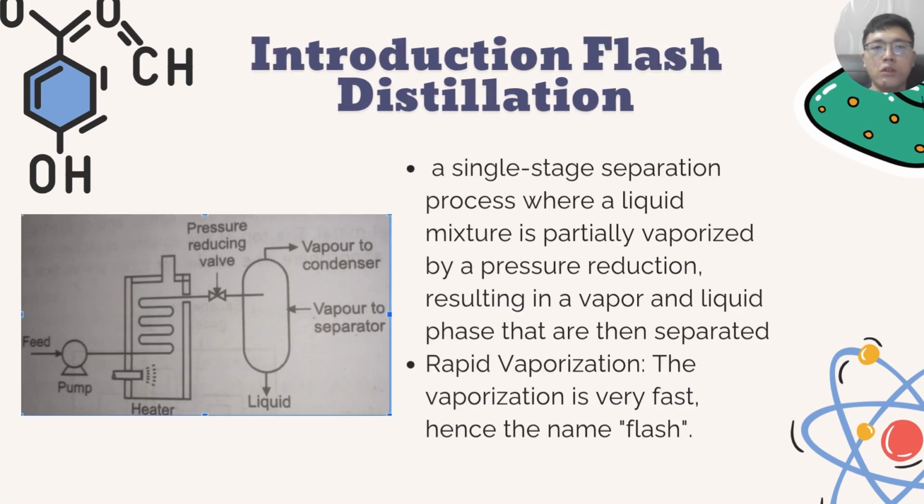So now is the introduction to flash distillation. Distillation is a single-stage separation process where a liquid mixture is partially vaporized by a pressure reduction, resulting in a vapor and a liquid phase that are then separated. And flash means a rapid vaporization, as the vaporization is very fast.